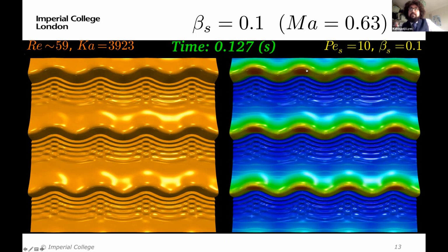So you will have Marangoni stress acting only in the spanwise direction, and that's why you have this type of dancing motion. Here it's a high concentration, and with the Marangoni stress it will diffuse this part of surfactant toward the front, and then it will go like this, and vice versa.